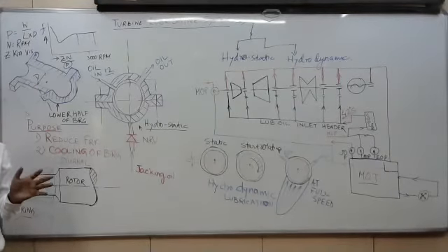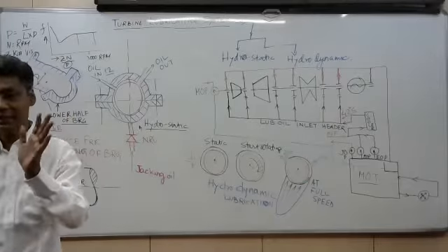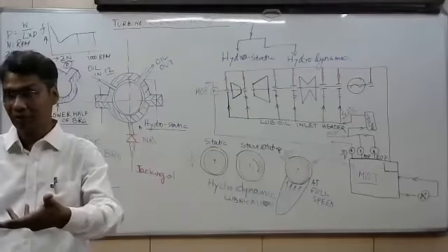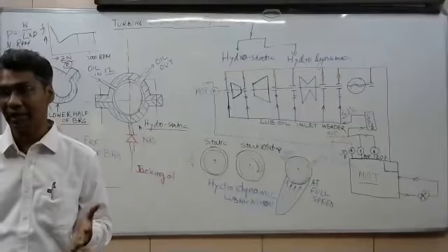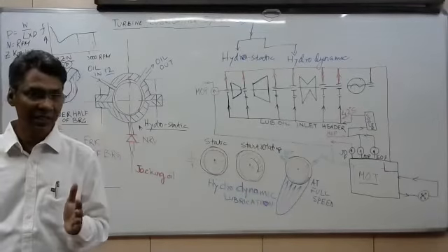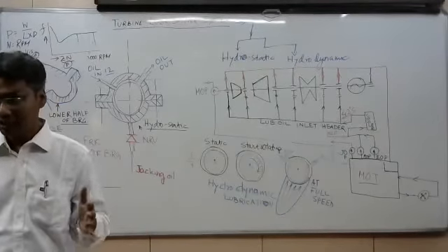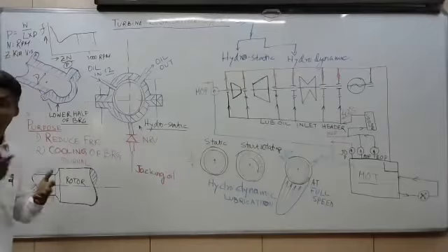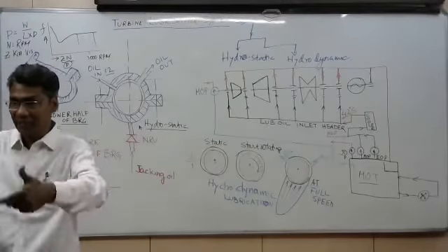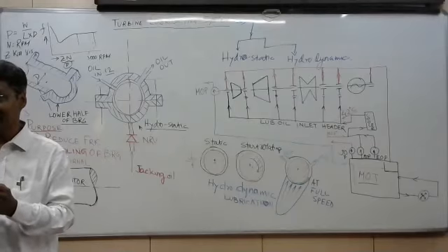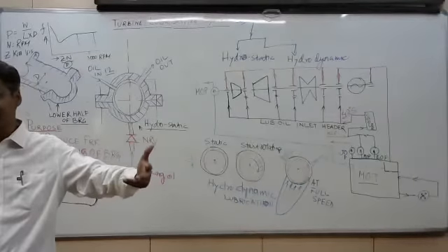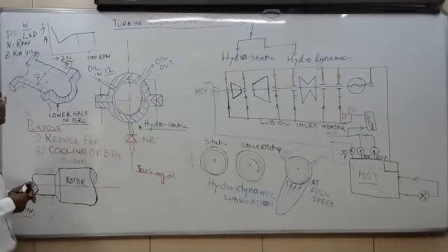So we have to design the bearing length and diameter depending upon the load. If the load is higher, the length or diameter may be higher. If the load is less, the length may be less accordingly. Because the oil film which is created below this has some load carrying capability, so we have to increase the oil film length. How the oil film forms, I will explain.